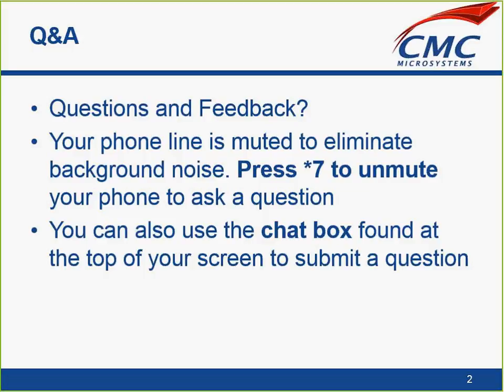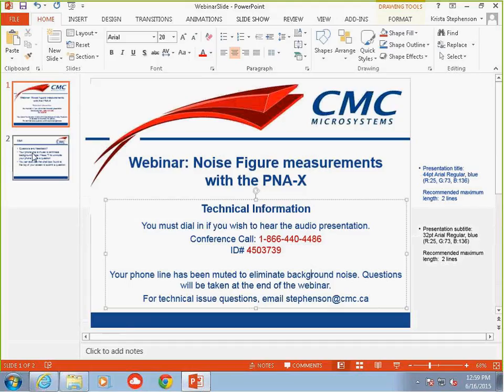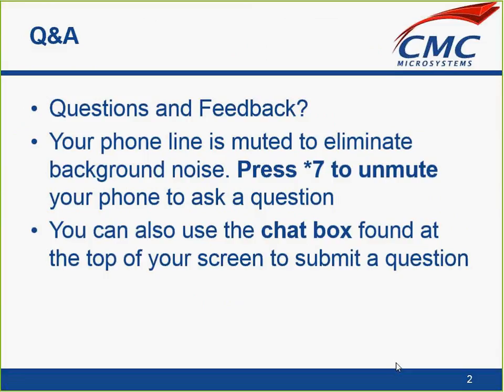You might be able to do that with our new spectrum analyzer mode available in the PNA-X, but that still might be reserved to a higher dynamic range spectrum analyzer mode. But in both cases, that is correct, we can make those noise measurements with receivers. The other question was the highest frequency for noise figure measurement with the PNA-X. The highest frequency we can go with noise figure measurements with the PNA-X is 67 gigahertz using the measurement receivers and 50 gigahertz using the noise receivers. So a little bit of discontinuity there, but those are the frequencies for in the box.